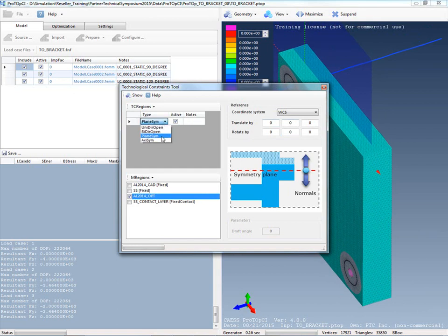I'm going to add an additional option here. It's called bidirectional open constraint, and this will be used for casting, like a casting form. As I show here, the casting is defined in a way that the casting form can be opened in those 2 directions. Those are capabilities to tell the optimizer in which direction it can take out the material. So that's all I have to define.